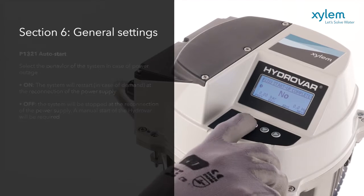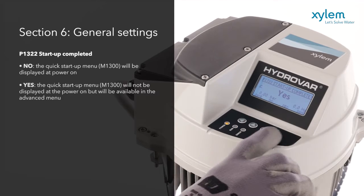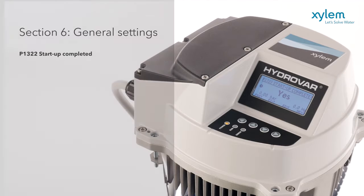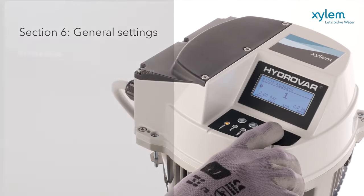The control panel will now ask if setup is complete. Select Yes to store the settings for operation. Select No, and the startup procedure is shown again at the next power-up. As long as this parameter is left to No, a warning will be shown to prompt the completion of this information. There are 10 minutes to make this choice, or a warning will be shown to prompt the completion of this information.